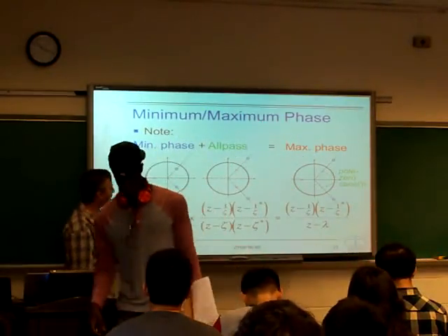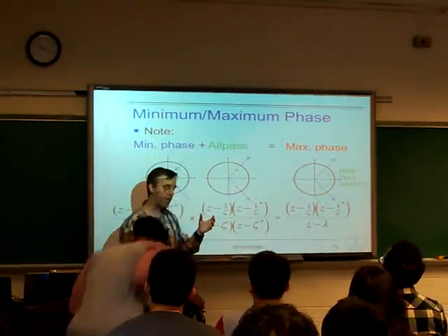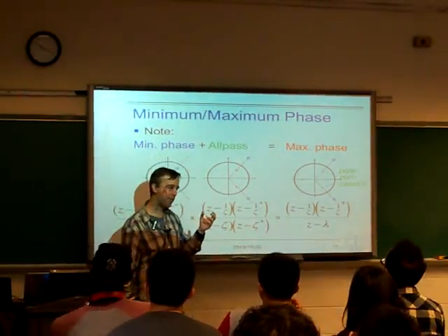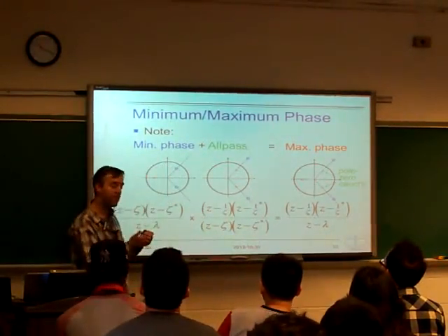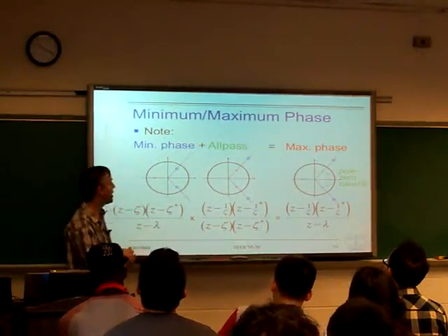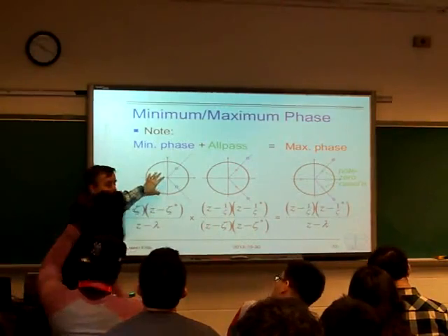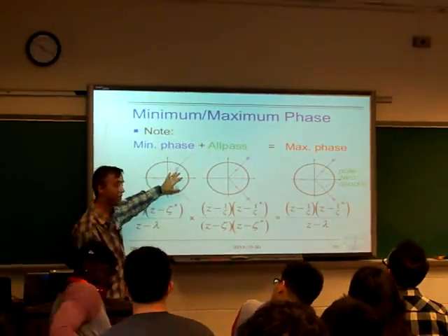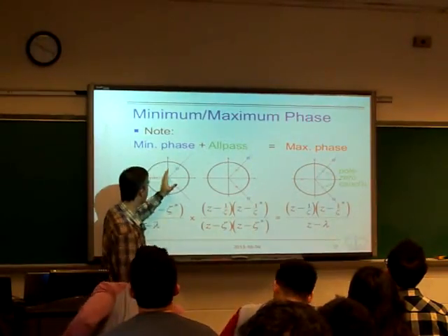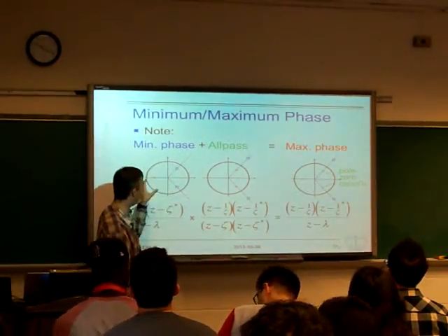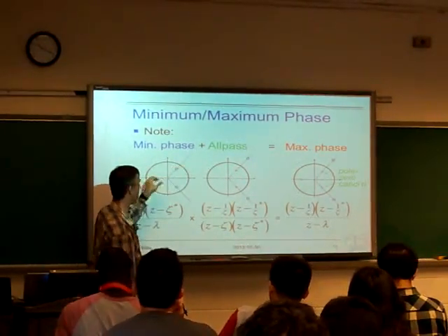Now, I introduced this by saying that, in the same way that the reciprocal roots in an all-pass filter have a balancing effect, if we replace zeros by the reciprocals, they have the same effect. Here's another way of linking the two. If we have a minimum phase filter like this, with in this case 2 zeros inside the unit circle, we can consider putting some signal through this system, which would cut the frequencies around here and boost the frequencies around here.